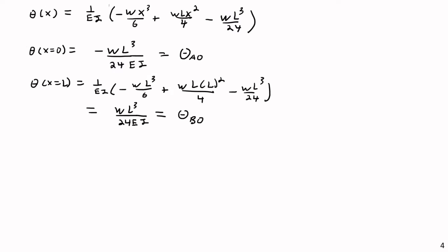We're going to need two secondary beams because we have two redundant forces that we removed. So let's analyze our secondary beams.